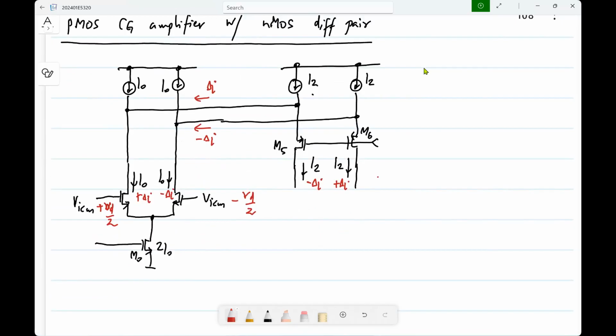So in place of NMOS differential pair plus NMOS common gate, now I have NMOS differential pair plus PMOS common gate. What will be the output resistance looking up? It will be gm5 rds5 times whatever is the resistance of this, plus of course the current sources themselves will also be MOS transistors, so that will also be there. Is this clear?